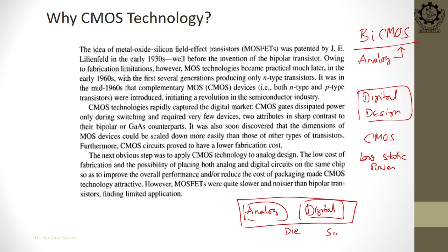So, it is known as the SoC, system on chip. So, previously if you see, the microprocessor is in CMOS technology, but if you have any analog block or module, they used to prefer the bipolar technology, but nowadays as CMOS has become quite mature and it is also offering quite reasonable performance for analog circuits also. So, nowadays we see that most of the SoCs are made in CMOS technology.